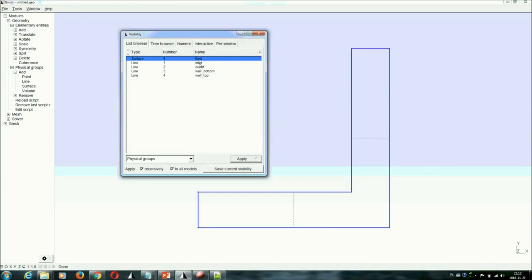I will make one more comment for users of QuickerSim CFD Toolbox. If your version does not support these text names, you will need to know that these physical group IDs are the way how you specify your boundary conditions in the solver.